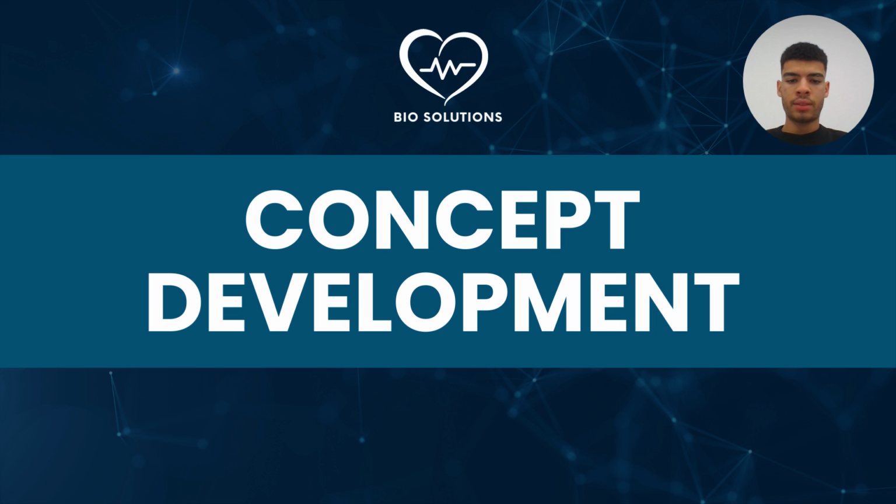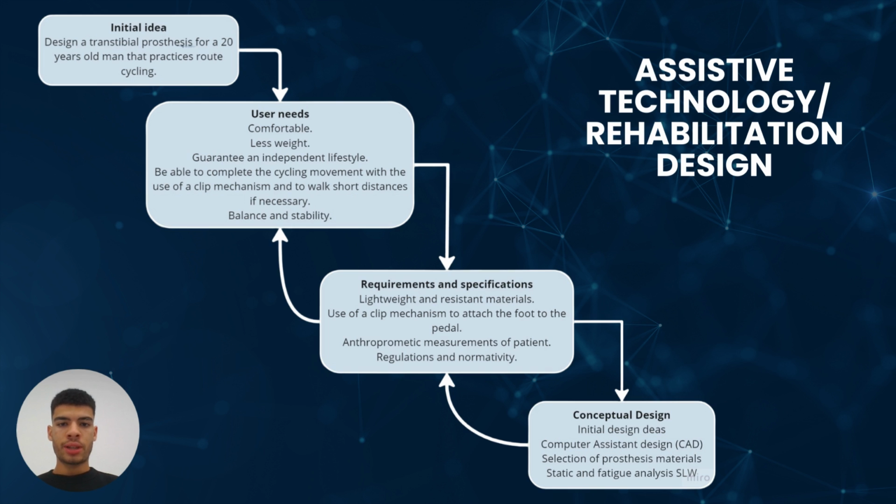For the concept development, the universal design methodology was used, starting with the objective established as the initial idea. Also, knowing the user needs, such as completing the cycling movement, ensuring balance and stability, and that it is comfortable and lightweight. The requirements and specifications of the prosthesis are that it is made of a resistant material, adjusts to the anthropometric parameters of the user, and ensures the use of the clip mechanism. And finally, obtain a conceptual design in SolidWorks and make the finite element analysis.